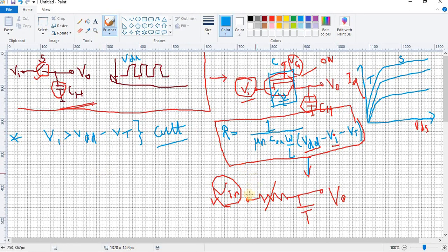To ensure the transmission from the input terminal to the holding capacitor, the value of input should be less than this particular value, right? So when we increase the input, we are effectively making our transistor go into the cutoff mode. So the basic working of this particular MOSFET will not work, right? For that aspect, we get the maximum boundary condition for the input value.